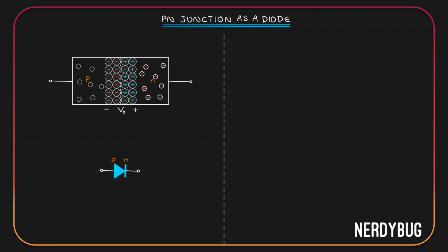The number of electrons on the p side is going to be Ni, which is the intrinsic carrier concentration, and the number of holes is going to be Na, which is the number of acceptor atoms we have added. While doping, we make sure that Na is very much greater than Ni, so the number of holes is very much greater than the number of electrons, which means most of the times we can ignore the existence of electrons. So, to show that there is still electrons in the p side and their number is very less, let me add one electron over here.